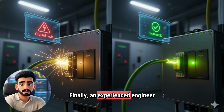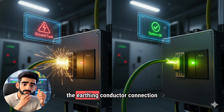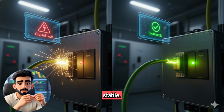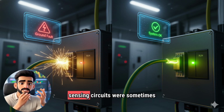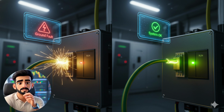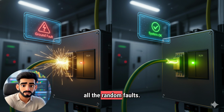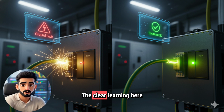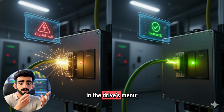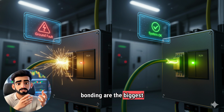Finally, an experienced engineer examined the panel grounding layout. It was found that the earthing conductor connection was loose and the drive's reference was not stable. Because of this, the sensing circuits were sometimes detecting false ground faults. Simply cleaning and tightening the earthing joint resolved all the random faults. The clear learning here is, not every fault has an answer in the drive's menu. Sometimes, basic grounding and bonding are the biggest culprits.